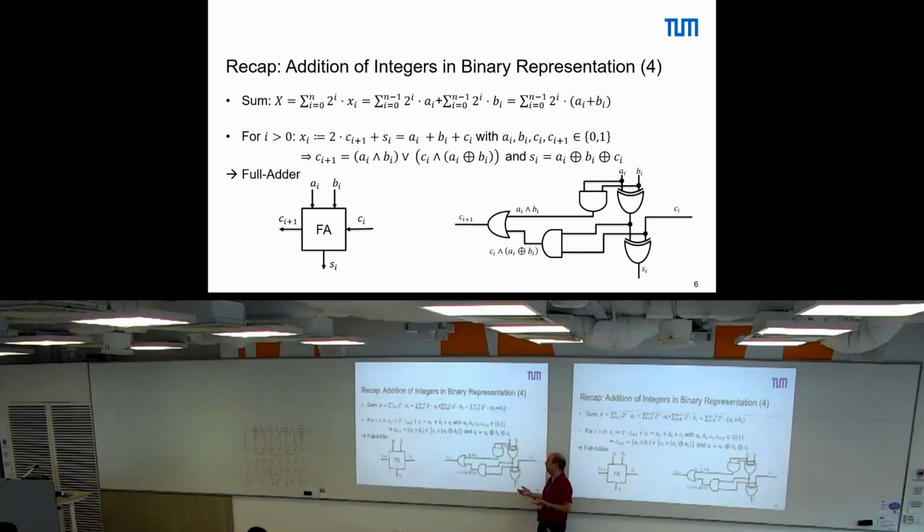And now my question is, why do we care? So one obvious thing is that if we remove them, we save area. But besides area, what else changes? It's faster because each gate adds to our delay. Each gate is a capacitor. What else?